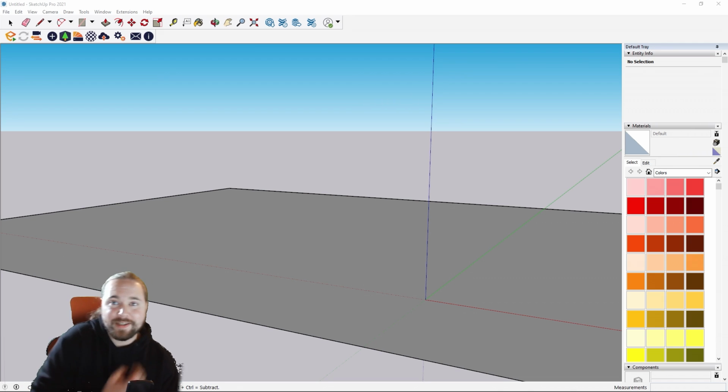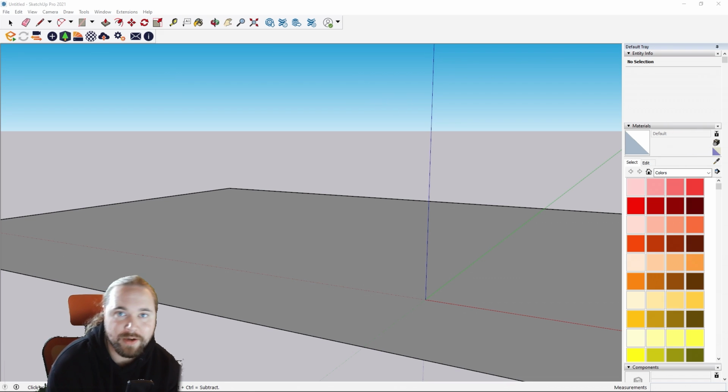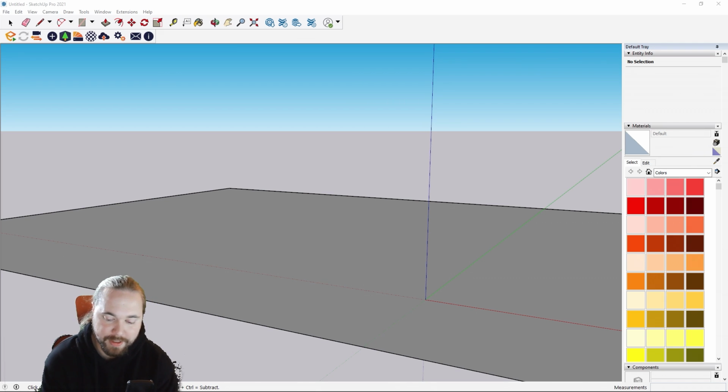So custom assets or 3D models. What kind of 3D models can we use and where can we find those? Enscape can import 3 separate file types as custom assets. Those are called FBX, OBJ, and GLTF.